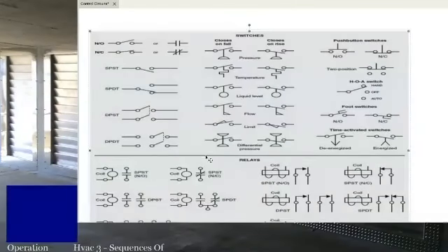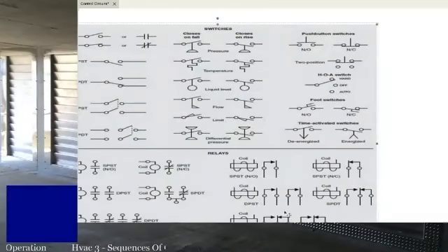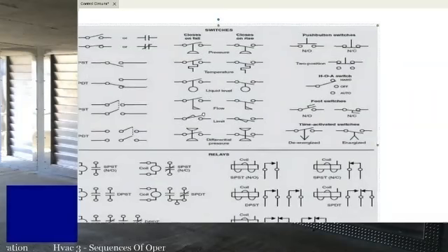So your most common ones, right, are especially your switches. Make sure that's centered up pretty good. Yeah, so center that screen basically. Switches: closes on fall or closes on rise. You got pressure, temperature, liquid level, flow switches, limit switches, and differential pressure. Those could look different, but that's a pretty common way to show all those.